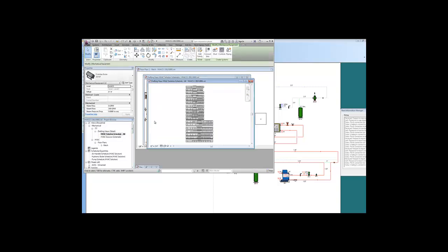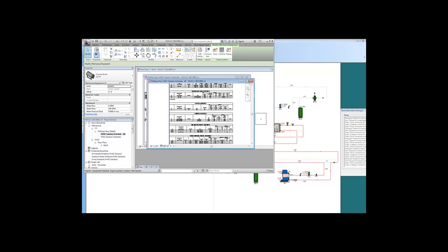The schedules here are in the drafting view inside of Revit, and it brings them in all at one time, so they're not modifiable. So back to that add-in, if you do the schedules this way, it just brings them all in at once. If you map them and transfer it, then you can create the schedules inside of Revit. And then once again, the schematic, you can put in that drafting view as well.